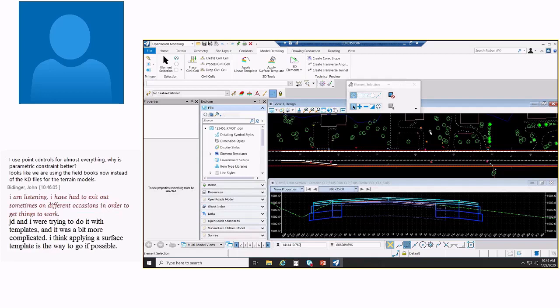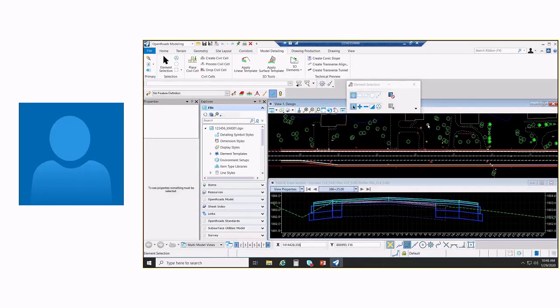And then what Eric said he didn't get to show was creating your existing surface through template. That's really kind of like what he showed in the beginning, just using his feature constraints and how he was tying things into the edge pavement. And just your template would represent the existing pavement rather than the proposed stuff. But we can do a video for that as well.